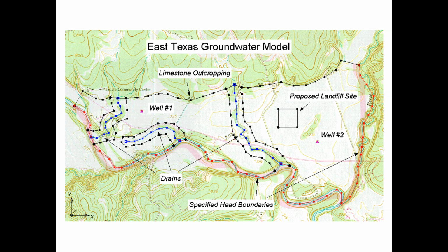And let me go back here to a different color. And then this boundary up top, this is where the alluvial fill in the valley pinches out, and we have some limestone bedrock outcropping there. So this is a no-flow boundary condition.